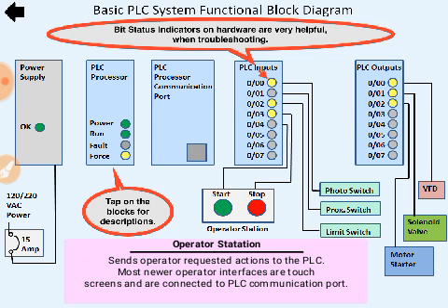Another one is the operator station. It says it sends operator requested actions to the PLC as 0 and 1 binary information. Most newer operator interfaces are touch screens and are connected to the PLC communication port.